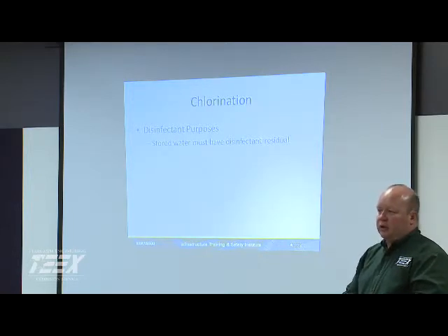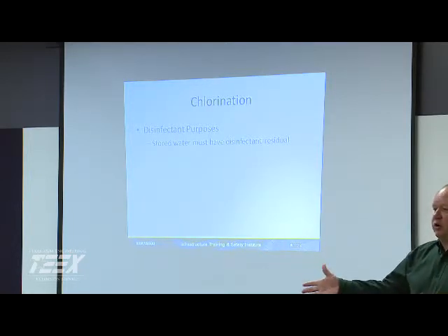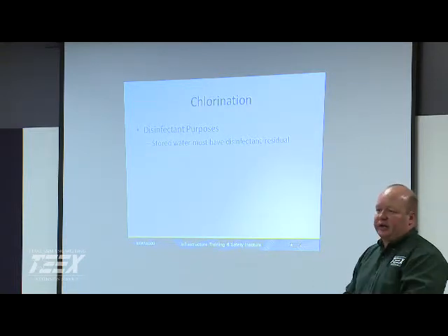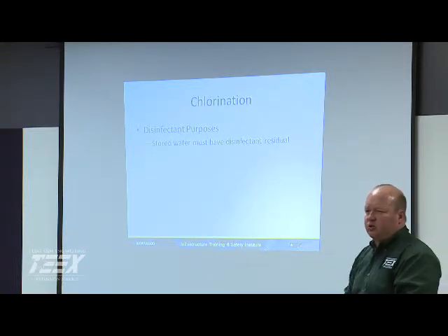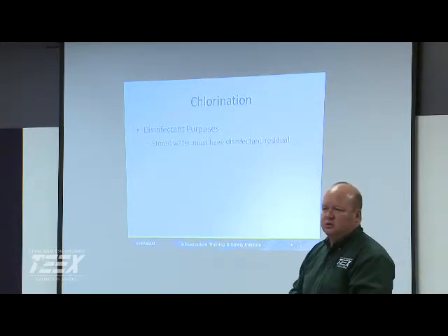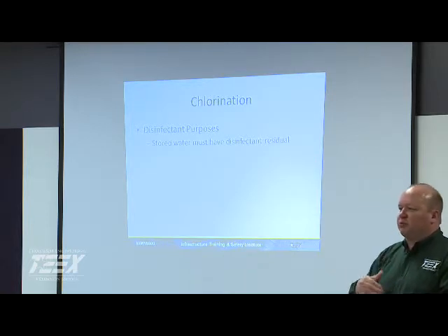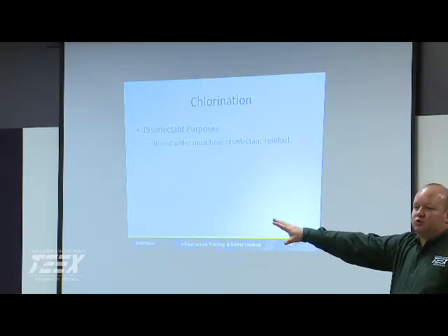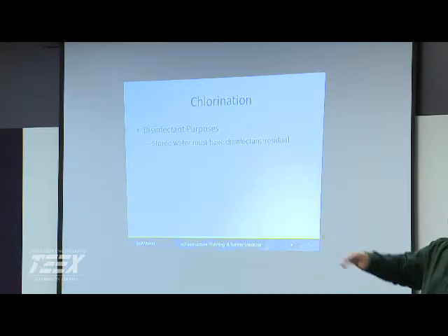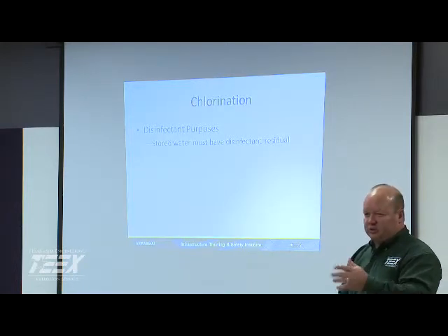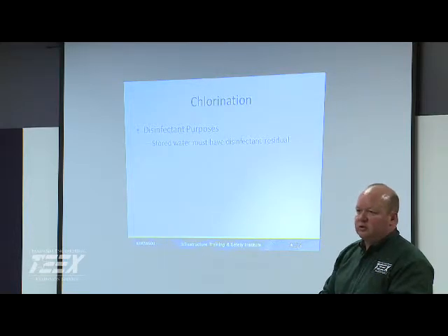Yeah. And it can be beneficial if you're looking at water age, if you're looking at disinfection byproducts. You don't have to come out so hot out of your plant. What are y'all pushing out of your plant? What's your target? Usually we go about 2.4, 2.5. For us, that was coming out pretty hot, because we can boost it further out when you start to look at your secondary stations. But what's your TOCs running? Usually we can claim a 1 on them.